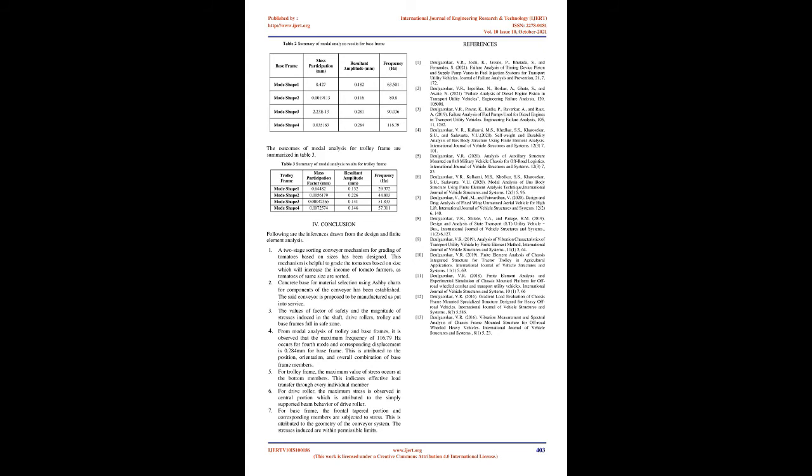From modal analysis, the mode shapes and frequencies are evaluated. In addition to this, mass participation factors in X, Y, and Z directions are devised for base and trolley frames. The mass participation factor signifies the amplitude of displacements corresponding to each mode shape. The magnitudes of mass participation factors in X and Z directions for base frame are negligible as compared with those in Y direction, while for trolley frame the magnitudes of mass participation factors are considerably increased, however still their magnitude remains less than those in Y direction. The outcomes of modal analysis for base frame are summarized in Table 2.